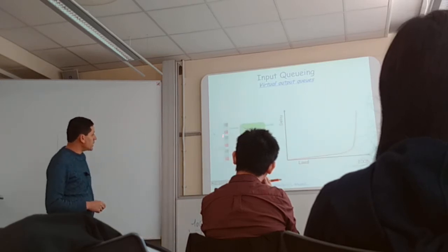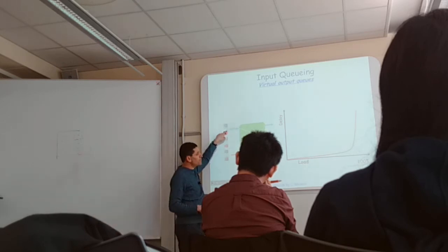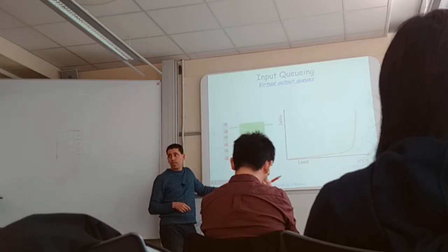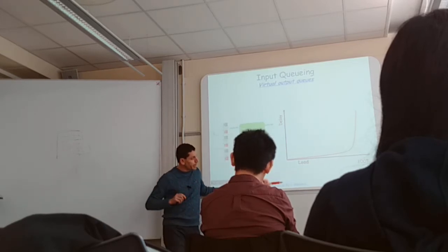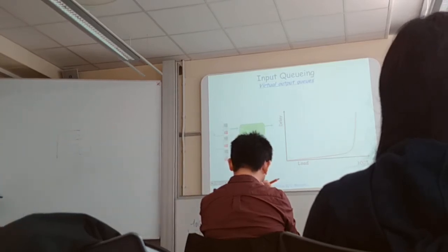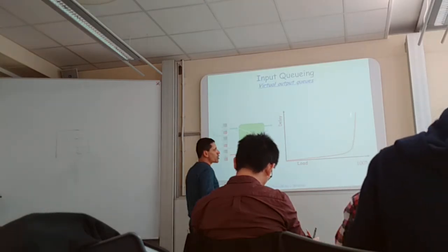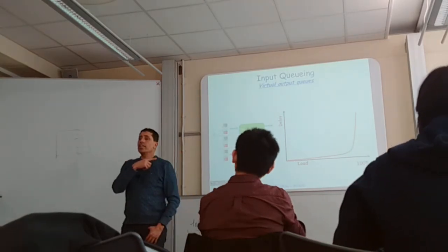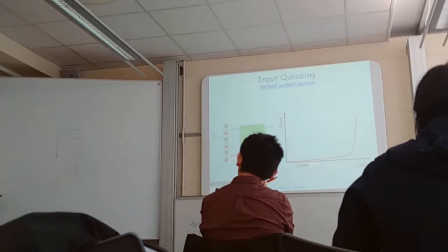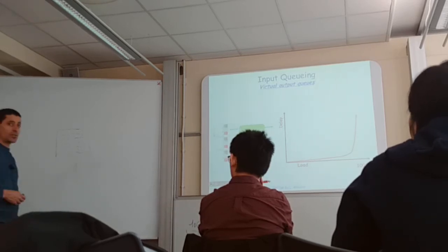And here it says if I have an input queued router with virtual output queues here, I could potentially have 100% throughput. Okay, guys, sorry, I did not stop. I will stop in 2 minutes. Sorry, we moved on. Let's continue these 2 slides before we move there. Okay, so if I have VOQs, I will have 100% throughput potential. This solely depends on the scheduling algorithm, on the arbiter. If you design a good arbiter, you will have 100% throughput. If you design a not good arbiter, you will not have 100% throughput.